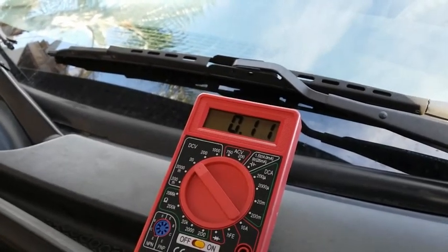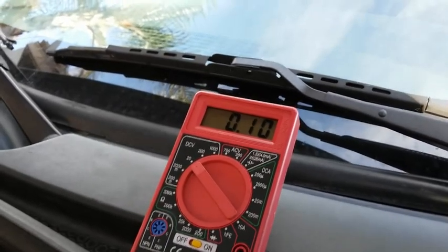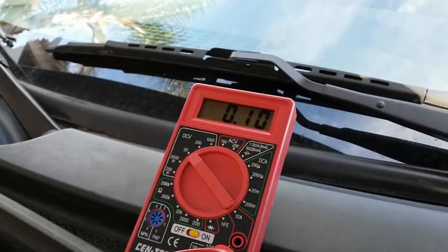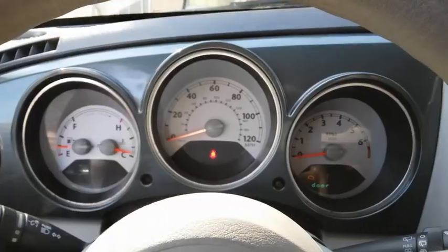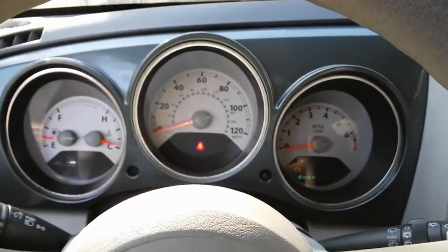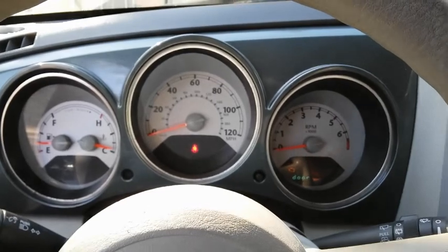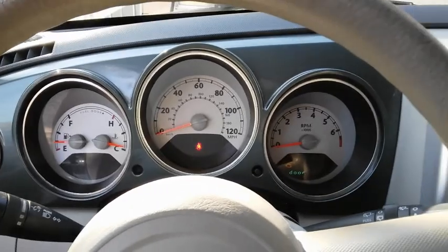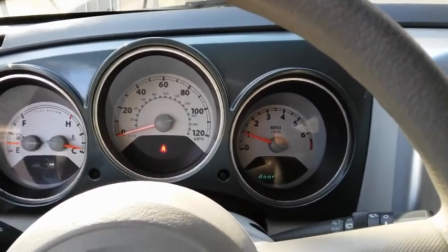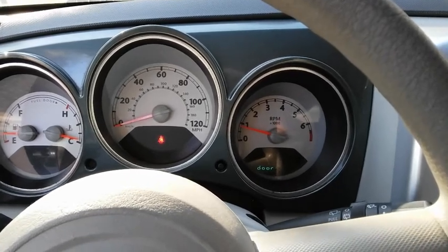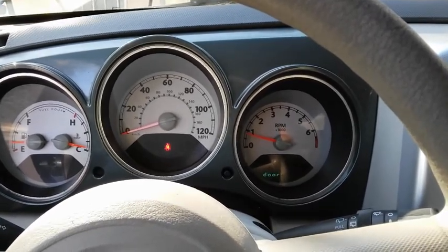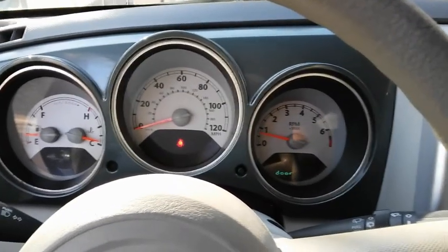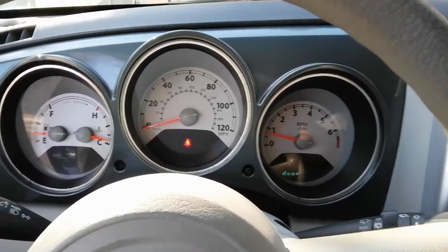So the next step I'm going to do is go back to the vehicle and start the engine to see if we capture that intermittent problem with the oil light turning on. Alrighty. So I'm going to start the engine now. This is now with the key on, engine off. I still don't see an oil pressure switch light on, but I'm going to start the engine now. Still, this is with the engine on. So far, it looks good. But during that initial shutdown, we saw that little glitch just for that split second where the voltage dropped and then went back to 12 and dropped back to 0.